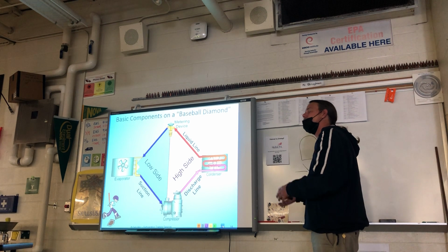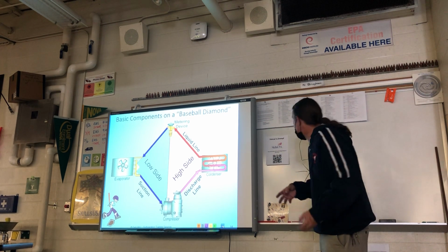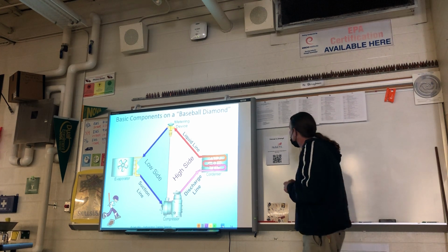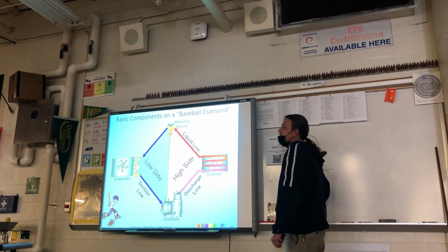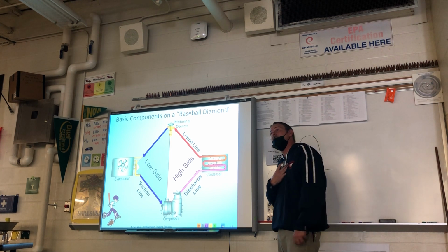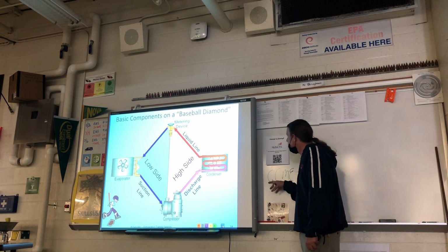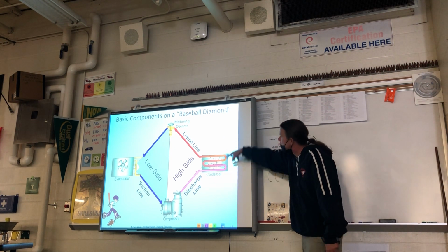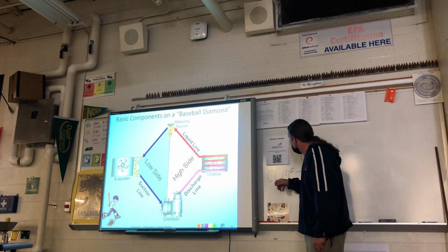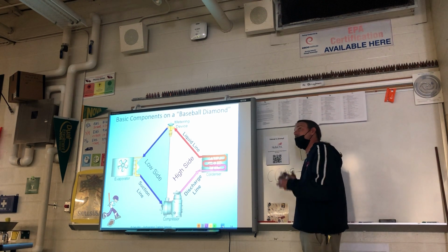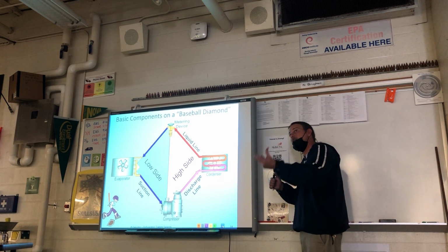Home plate, first condenser, second metering device, third. And if you can't remember that, if you could remember CCME, CC me? No. CCU? No. CC me. CCME. If you can remember the four letters CCME, you can remember compressor, condenser, metering device, evaporator. You got the four components. So then in your head, all you got to do is connect them up with the lines.